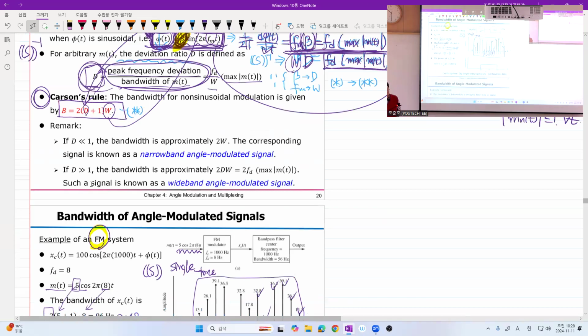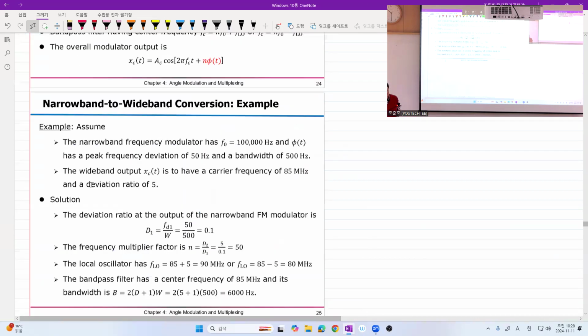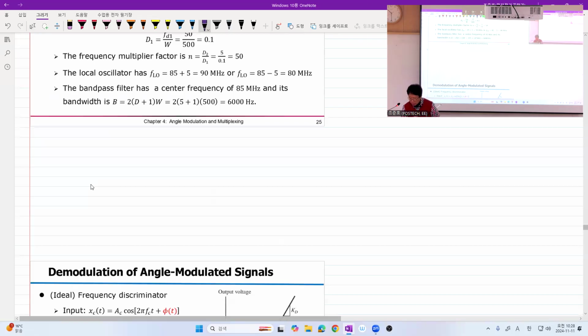So first we approach the design mathematically. So here is the angle modulated signal. And this contains the message in the form of an affine function, or its derivative is an affine function of the message in PM and FM respectively. And the problem is that this is the input up to the power amplifier in the transmitter.